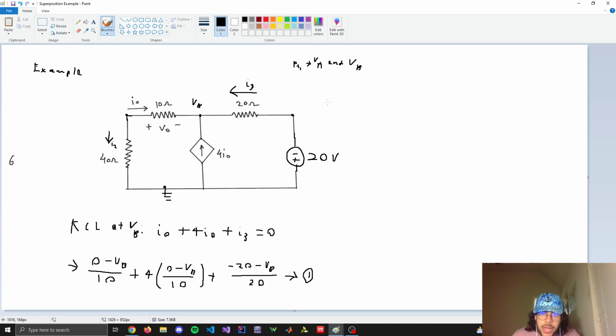And now that we have this VB, this is going to become VA plus VB plus VB, because this is part 1, and then this is part 2. We have to add these two parts together. And then you can solve for that voltage, which is going to be VA minus VB, and VB is just 2 VB, so that's going to be a number. So all you need to do is, that's how you do superposition. Honestly, the part that takes the longest would be solving these systems of equations. It's just a lot of algebra and it's really tedious. But that's how you do the superposition principle.